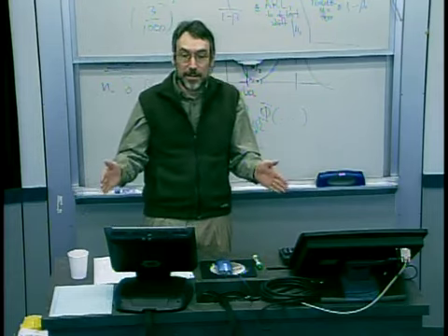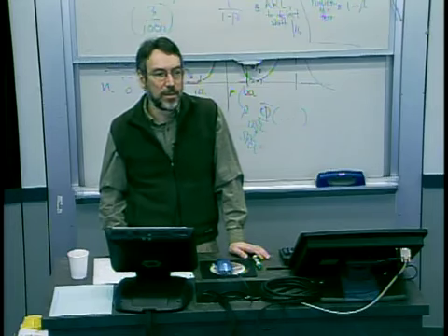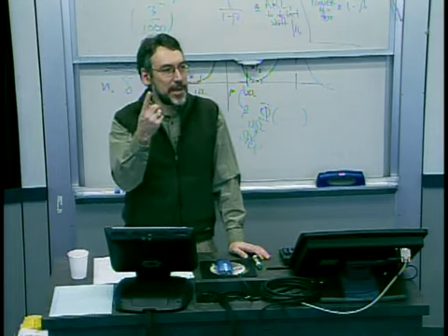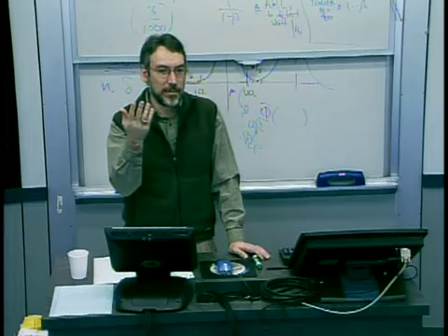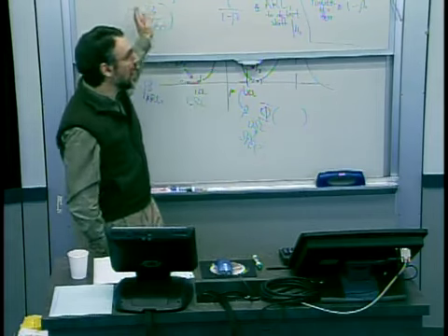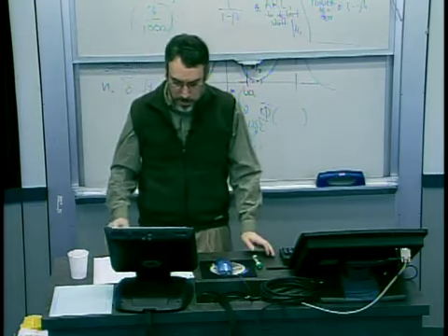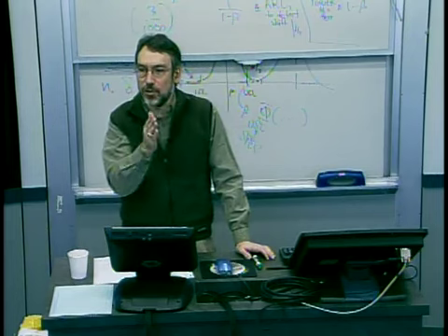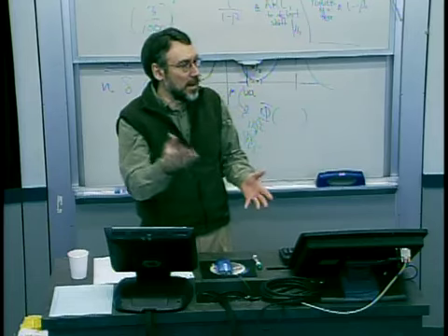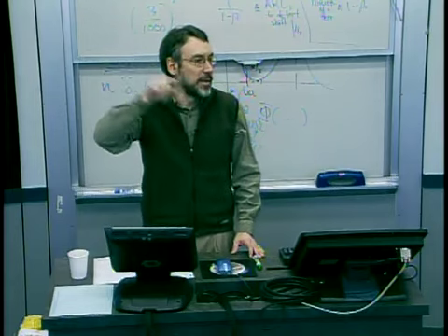So let's say that indeed I see, yes, that part looks like it's outside of the control limits. What's another thing you might do? Do you look just at that one single point? What other data do you have? You can look at the trends, so like Western Electric. Exactly. So now you can look back at the control chart data that has been plotted either manually in old systems or in the computer system. Track back historically and start to look, is there some other evidence that wasn't triggering an alarm, but that might give you a sense? And a telltale one might be, in fact, a slow drift in the points.